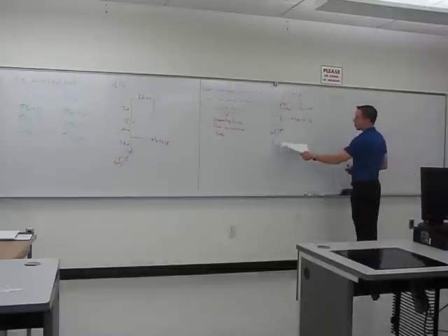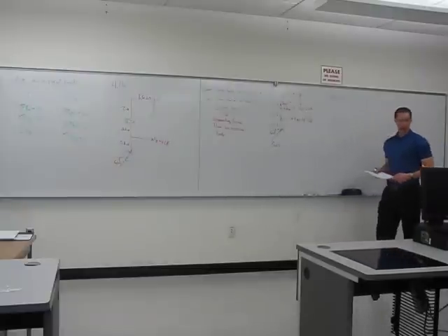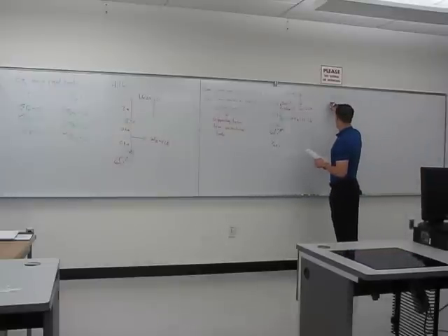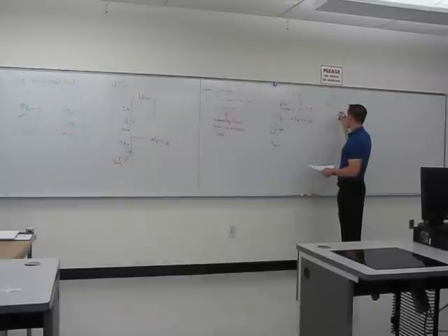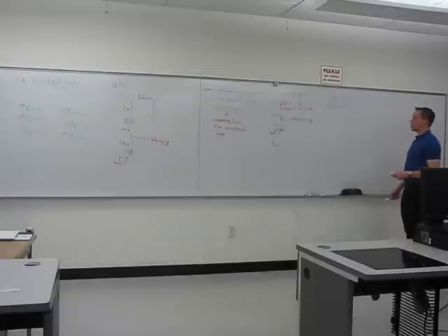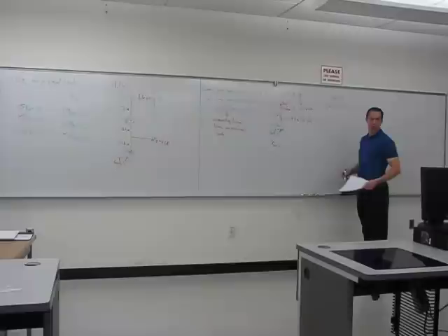So we have a component of Fa that is in the x direction. So we'll have here Fa, and then it's going to be the cosine of 60 degrees if you want the horizontal component. Plus, we have 4 pounds at Fb. So for the time being, I'll just leave it in the most general case. We'll put the numbers in later. And then we have Fcx, which I assumed is to the right, so I put plus Fcx equal to 0.